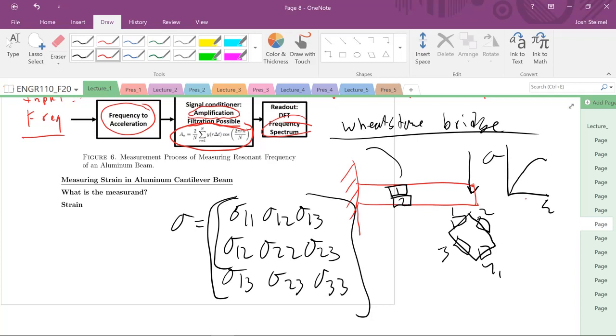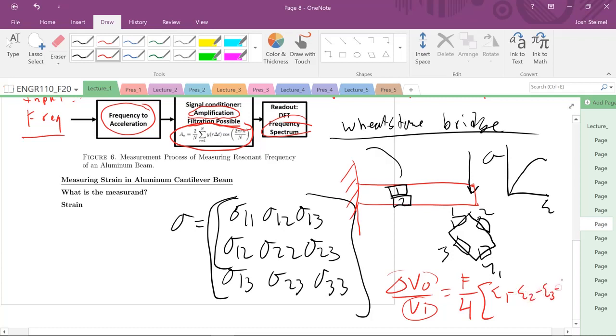We're going to use this fundamental equation: the output voltage that we measure as a function of the excitation voltage over the gauge factor over 4 times the strain in each arm of this Wheatstone bridge configuration. Again, much more on this later, but let's focus on the general process of how we analyze and measure these different experimental processes.